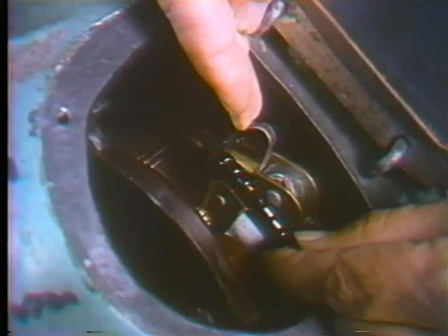But we aren't completely through with the series circuit yet. If you think back, you'll realize why. We only eliminated part of the series circuit, up as far as the brushes. We said these brushes can be trouble spots in a DC motor, and it's true. You'll find that they're worth checking. We'll go back to the holder where we didn't get a reading and continue. Let's put the brush back and reset the tension.